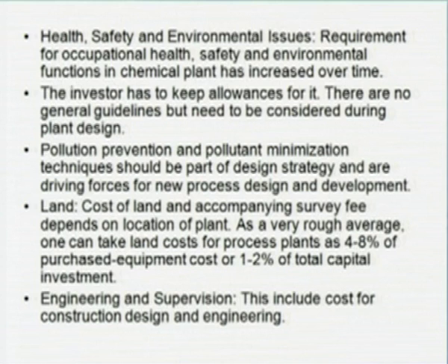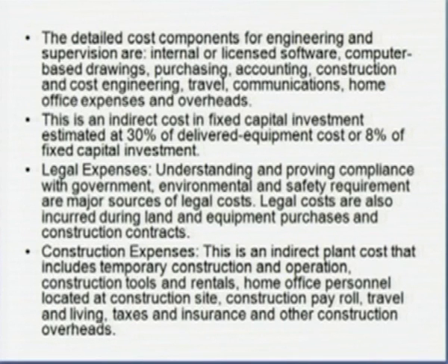The engineering supervision includes the cost for construction design and engineering. The detailed cost components for engineering and supervision are internal or licensed software, computer based drawings, purchasing, accounting, construction and cost engineering, travel communication, home office expenses and overheads. Now, this is an indirect cost in fixed capital investment, estimated at 30% of delivered equipment cost or 8% of fixed capital investment.